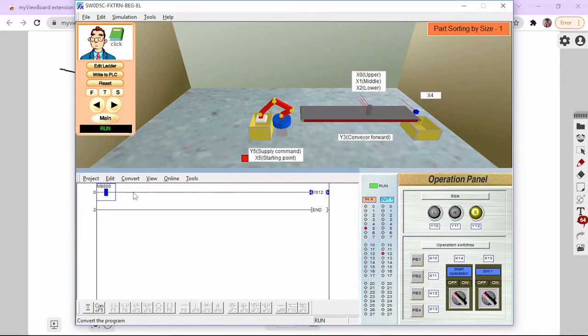Now, why relays are important is that timers, counters, or sensors which are being shown as input devices cannot in all cases output the current or the voltage that the output device would need to function. So that's why relays are always used. So in place of putting a timer or counter directly to start an output device, there's always a need to use a relay. So let's just show an arrangement of a relay.